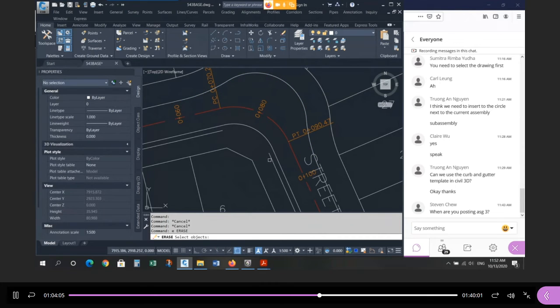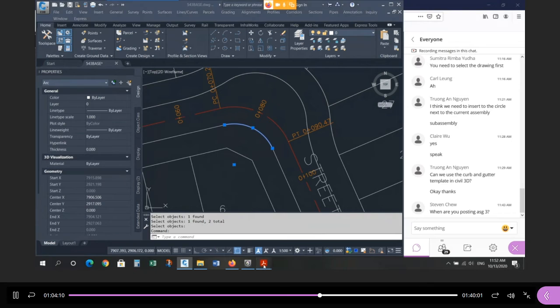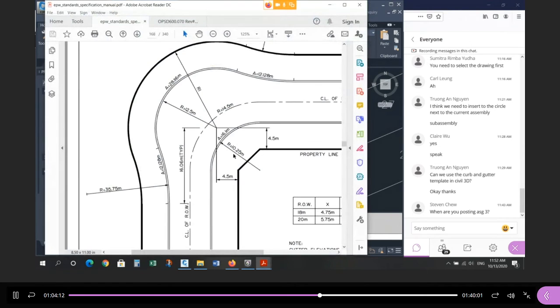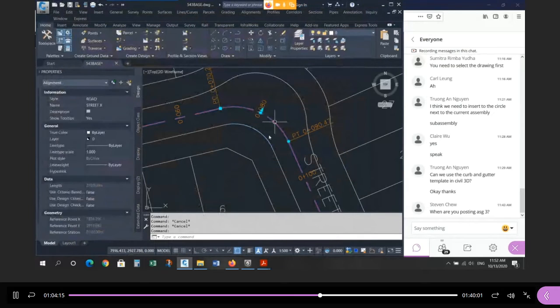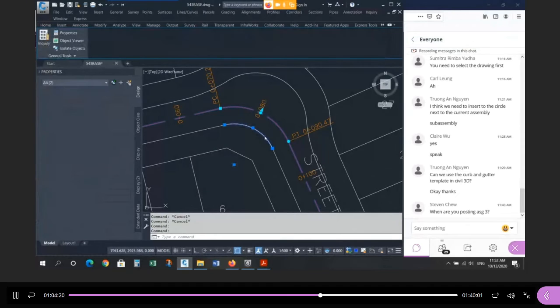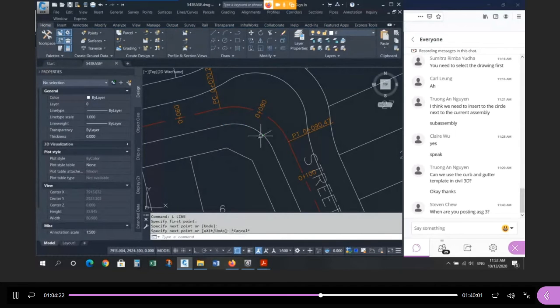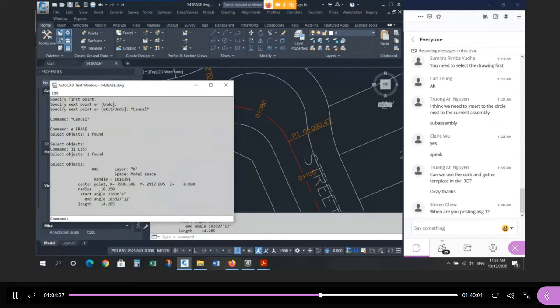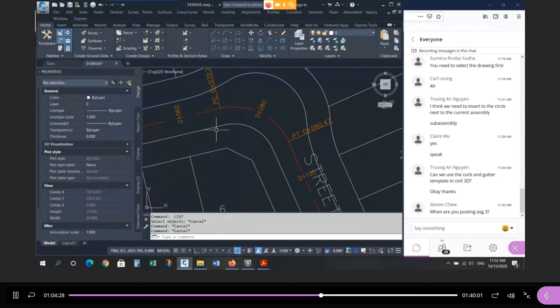Okay, and then you don't need these construction lines anymore. On the inside, it actually has a radius of 10.25, which, if you do the math, is parallel to the inside. If you offset the inside to here by 4.25, if I list this arc, it's already 10.25. So it's symmetrical. So your cross section is only getting wider on the outside, not on the inside.